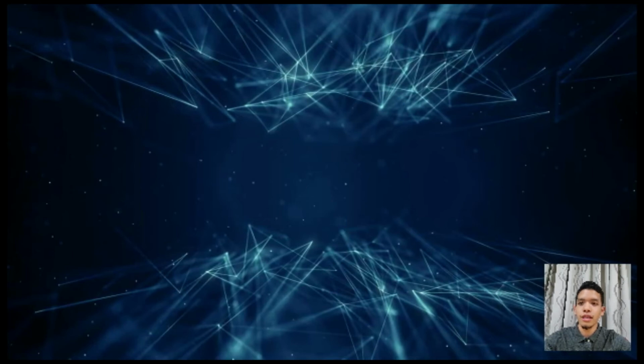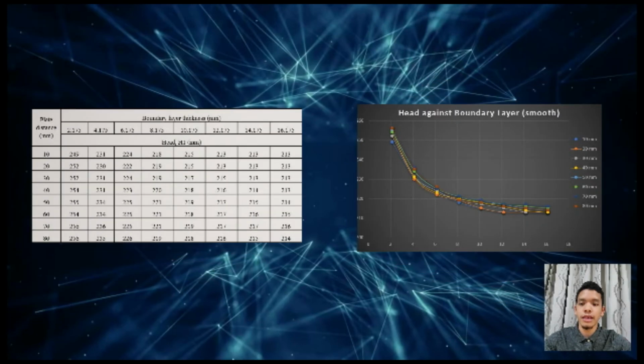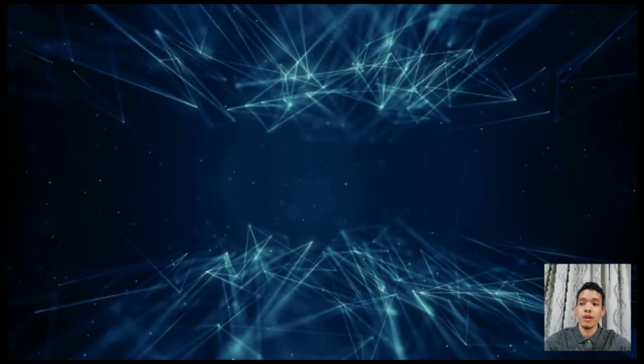So from experiment 2, from the data we obtained and from the graph, we can see that if the boundary layer thickness increases, the height recorded will decrease. This is due to the increase in boundary layer thickness that will cause the pressure in the fluid flowing from the pitot tube to the manometer to become higher, and this will further push the fluid in the manometer, thus lowering the height in the manometer. Next, we proceed with velocity.